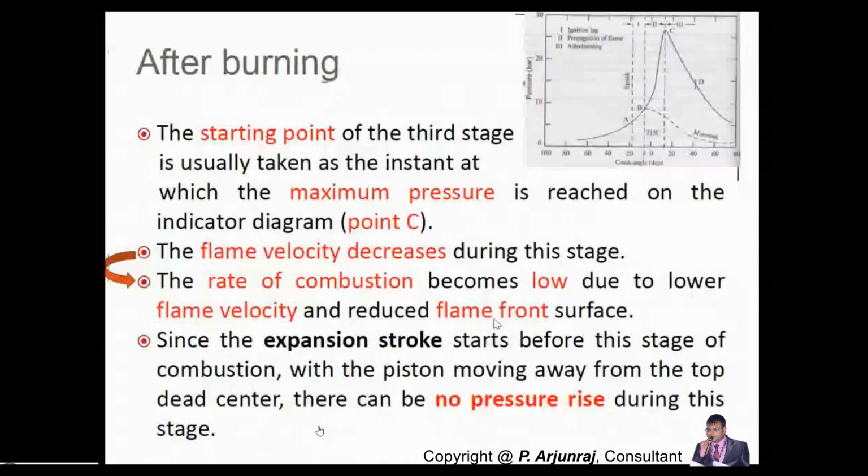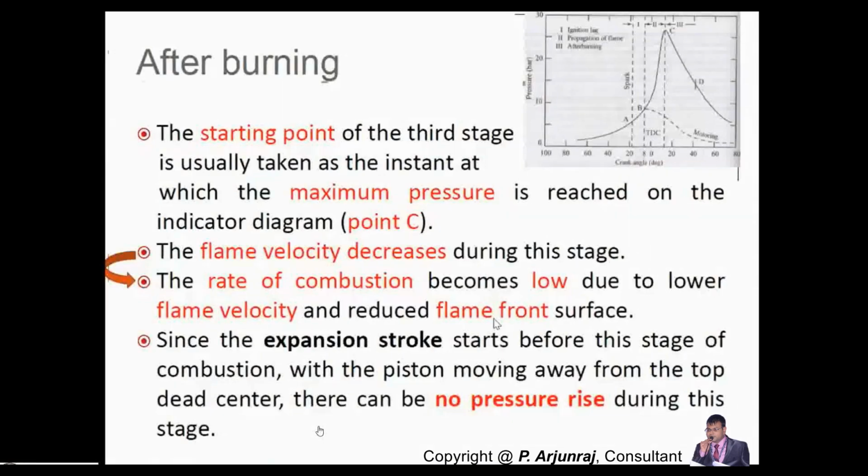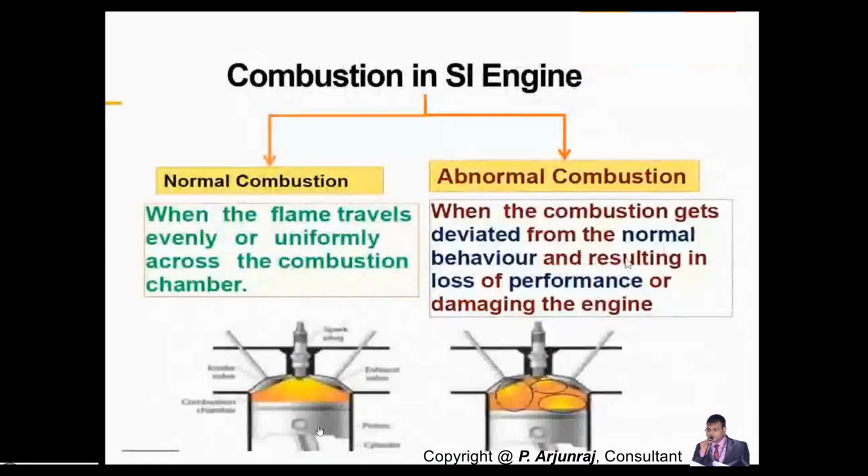What is the flame front? The flame front is nothing but what separates the burned gases from the unburned gases. And the last important thing is that in the case of the expansion stroke, obviously there will not be any pressure rise. Because we have seen the pressure versus volume diagram, in the Otto cycle and diesel cycle, where during the expansion stroke the pressure is reduced. The pressure is not going to be higher; the pressure is going to be lesser. So that's what is happening here in the after-burning stage. Okay, we will complete combustion in SI engine with this.